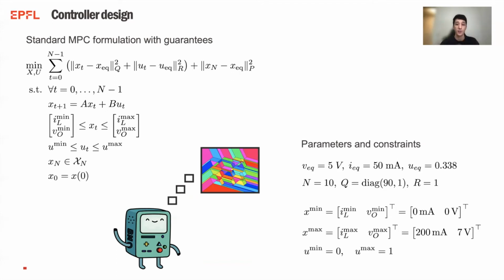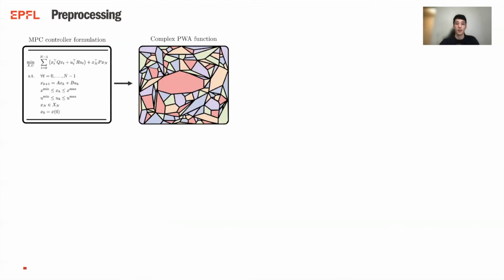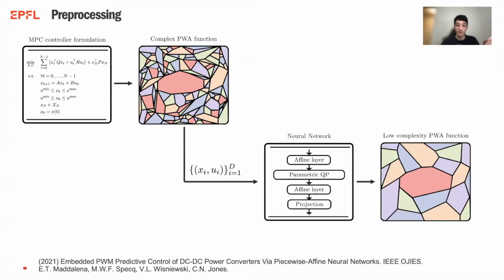This is exactly what we did. We used the multiparametric toolbox, MPT, to calculate the explicit MPC controller. But once we did that, we realized that the solution was simply still too complicated. It had too many regions. And the apparently simple task of finding in which region you were at every point in time and then extracting the feedback gains was already too much for the microcontroller to handle. This is when our very special controller simplification technique comes into the picture.